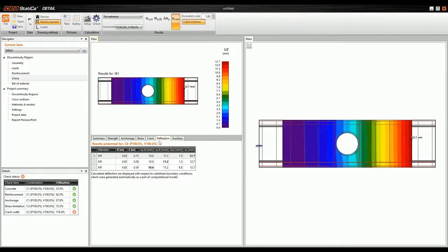The last step of SLS checks is the deflection. I have to mention that this example with the trimmed end is not really convenient to display the deflection, as the beam is continuous on both sides, so we are not really able to define some constraints at the end. For that reason, we are assuming such a constraint at the left end of the beam. In Philip's example, the deflection will be displayed in a much better way.